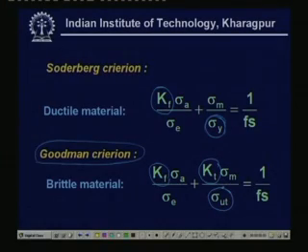So, it is customary to take up the value of the theoretical stress concentration factor for the sigma mean in the brittle case, whereas in the case of the ductile material one need not consider the value of Kt for design purposes.